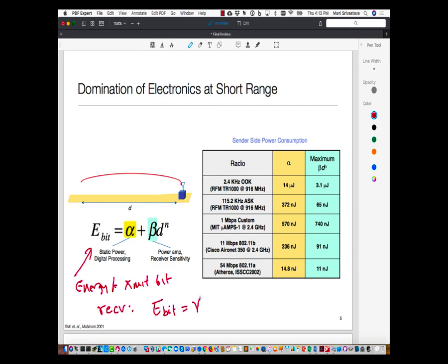So that brings a change in mindset for very short range radios, which is you cannot just passively listen, which is normally what is done in long distance radios, because listening is cheap and transmitting is expensive, so you transmit rarely, but you stay up listening for the transmitting.